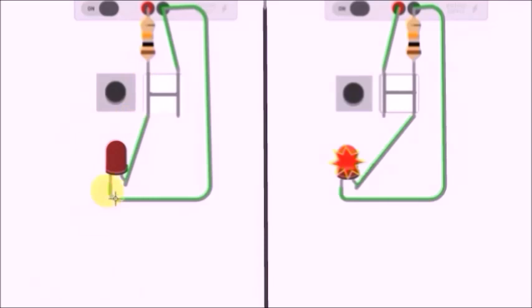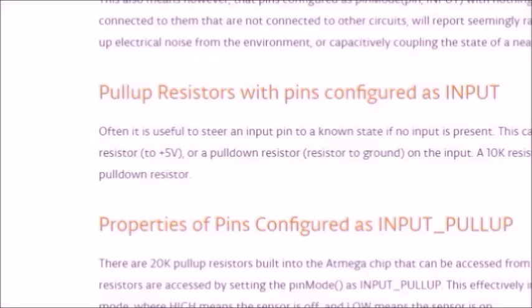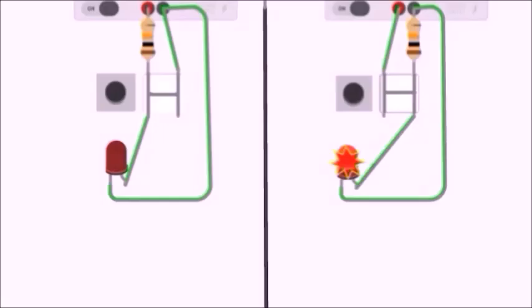I chose a 10K resistor. Why? Well, it is advised in the website arduino.cc under the headlining digital pin. This connection is said to be in pull up, and this one in pull down. Finally, why our button has 4 legs while we just used 3? It's for other kinds of connections, like for example, to use it with other buttons.